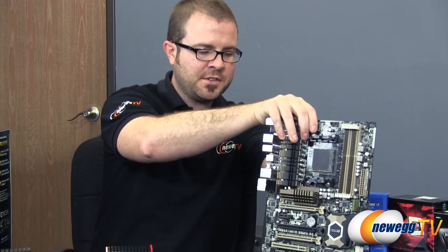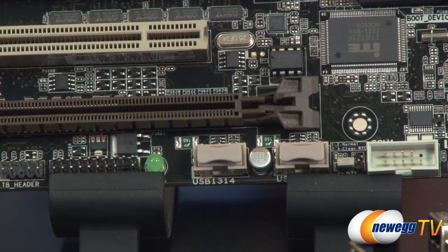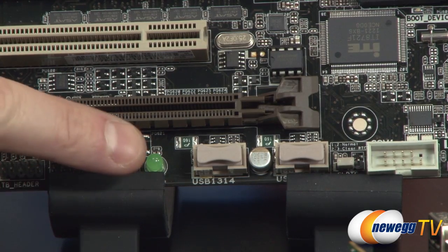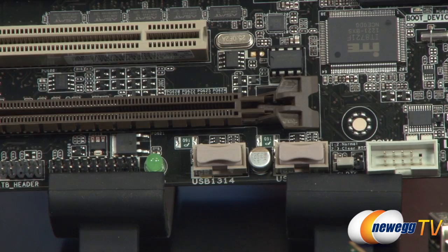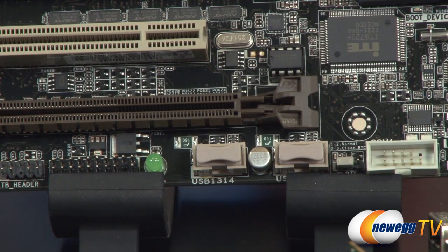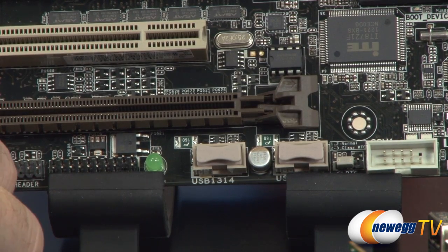And you'll find those features across lots of different manufacturers' boards, so those aren't necessarily exclusive to Gigabyte or anything like that. Here's a closer look at the Asus Sabertooth board that we're using as an example here. This is just a green LED. It's a light that turns on when the power is connected to the board and the power switch is turned on on the power supply. I found that to be useful just for a quick glance to know if the board has power going to it or not, because you never want to remove graphics cards or anything unless you've switched off the power from your power supply.